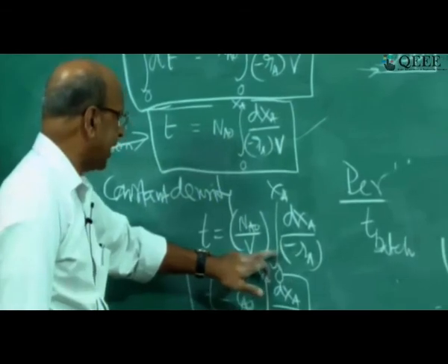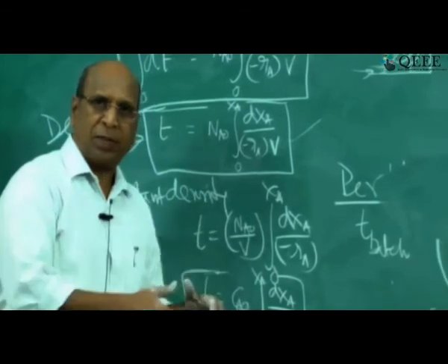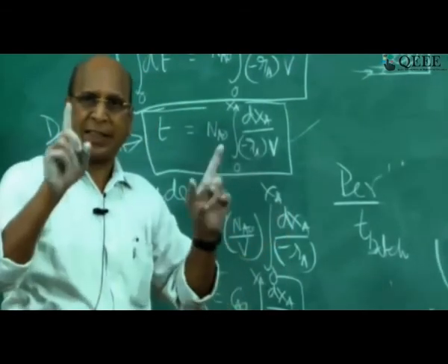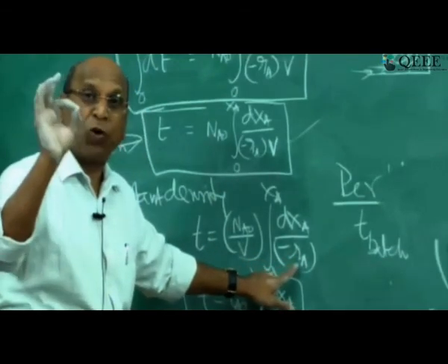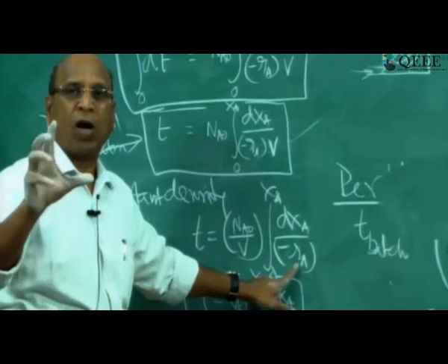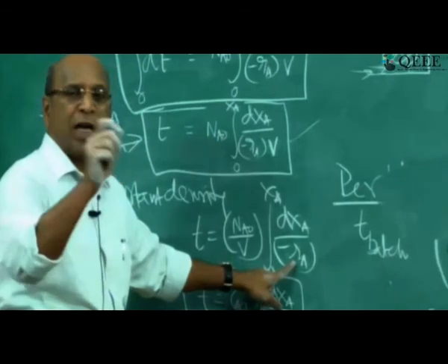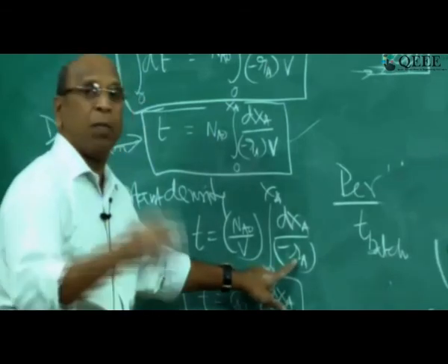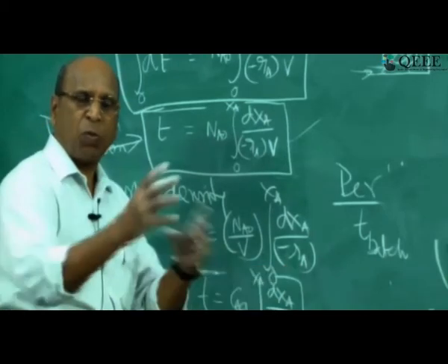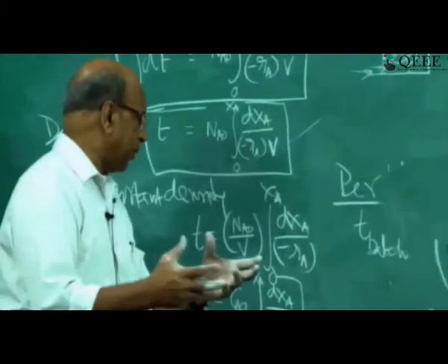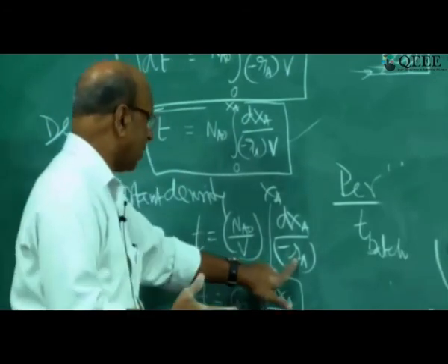The difference between a biochemical reactor and a normal chemical reactor is nothing except that this minus Ra is the rate expression for microorganisms. So now this minus Ra is not a chemical reaction like first order k times Ca, but it may be Monod's equation or Michaelis-Menten equation, or those modified with something. There are many modifications required for that.